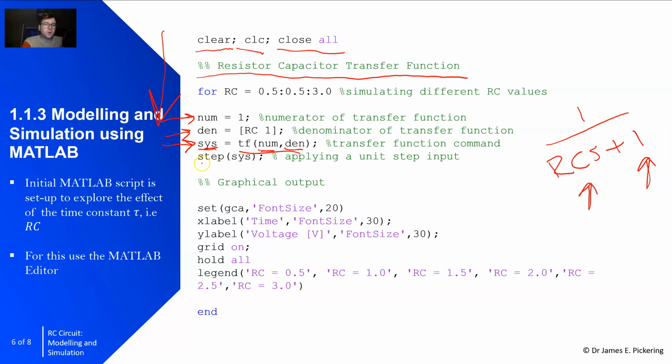What I'm initially going to apply is just a step input to the system. If you do step to system, in this case you can see I've called the system here, and hence why I've got system there. If you use the step command, it applies a unit step input. So it means that I'm effectively applying 1 over s to the system.